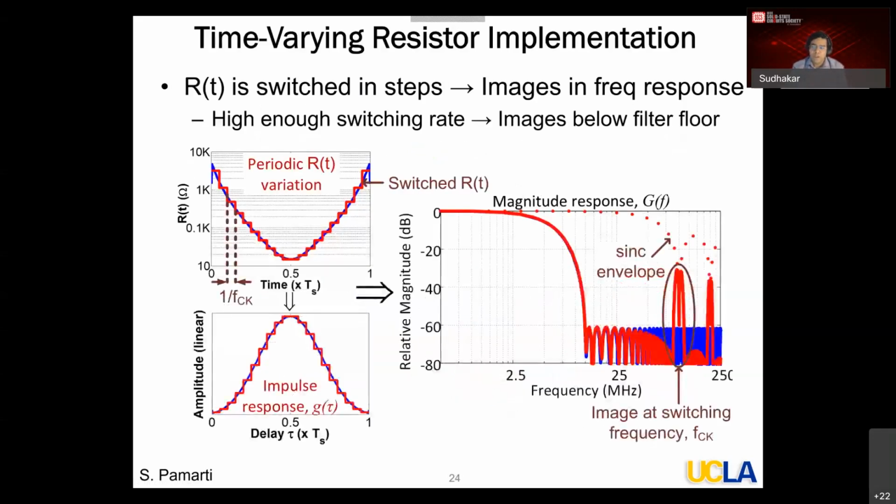Let me talk briefly about how we're going to change this resistor. Obviously, changing the resistor continuously over time will be challenging, but you can always change it in discrete steps. You can switch it. If you do that, you're going to get images in the frequency response.